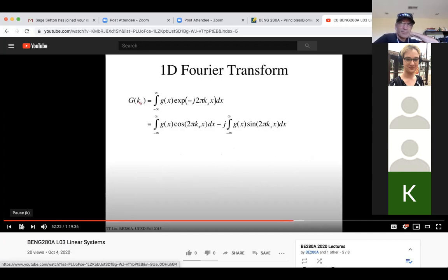So if we look at how the Fourier transform is computed, this is the equation. We expand this out with the Euler formula, such that we have a real part and an imaginary part to this integral. And note the integral is taken over an infinite duration. This is obviously modified to a certain extent in real life because we don't have an infinite signal. We have a finite signal, so these usually have finite integration.